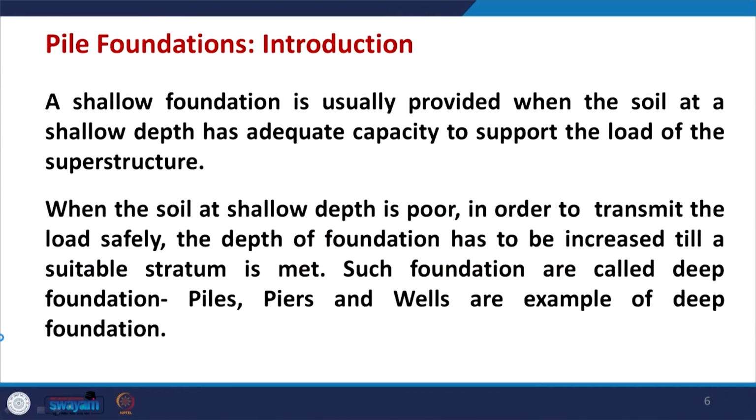However, when the soil conditions at shallow depth are poor, then in order to transmit the loads safely, the depth of foundation has to be increased till a suitable stratum is met, and such foundations are called deep foundations, where piles, piers, and wells are examples of deep foundations.